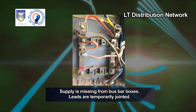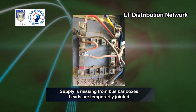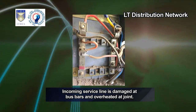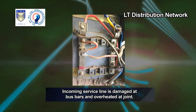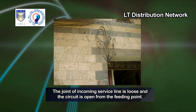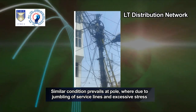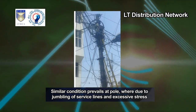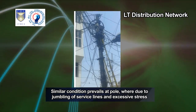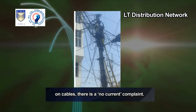Supply is missing from busbar boxes. Leads are temporarily jointed. Incoming service line is damaged at busbars and overheated at the joint. The joint of the incoming service line is loose and the circuit is open from the feeding point. Similar condition prevails at the pole, where due to jumbling of service lines and excessive stress on cables, there is a no current complaint.